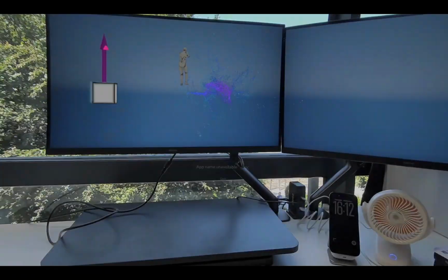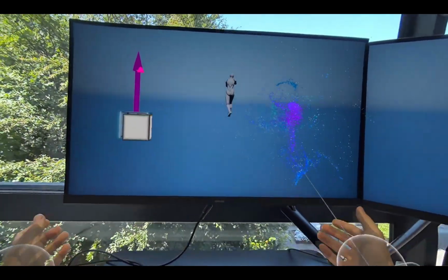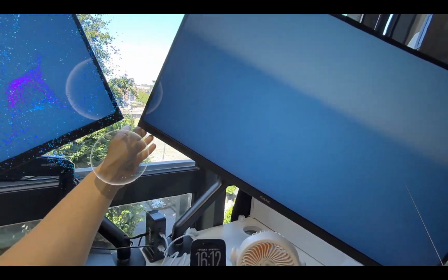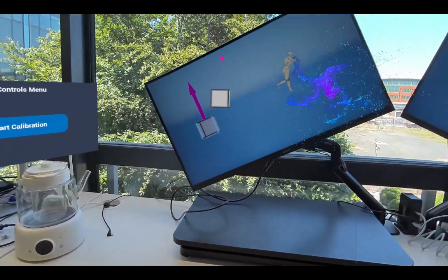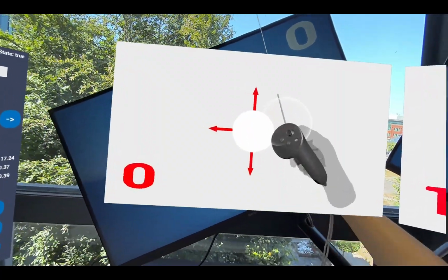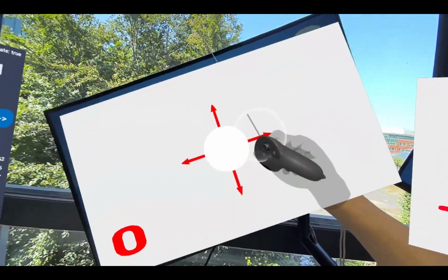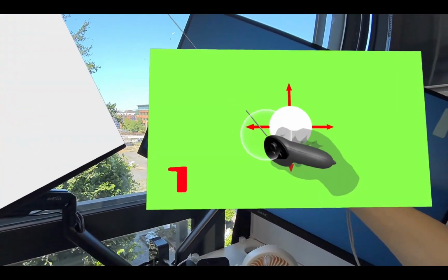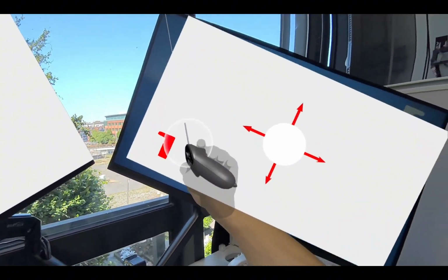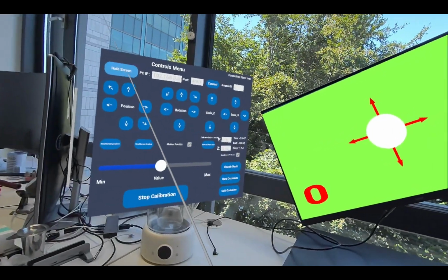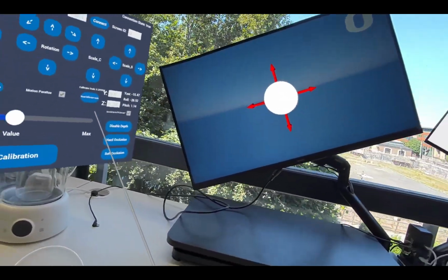In situations where the spatial relationships between screens are difficult to measure, such as this setup where the screens have been placed freely, we need to do more than align the primary screen calibrator. Enable Should Control PC Screen for each additional screen, and adjust each virtual screen so that its size, position, and rotation match the corresponding physical screen. The calibrated spatial relationships from the HMD will then be applied back to the screens in the PC nDisplay setup. This workflow allows screens of different sizes and arbitrary spatial arrangements to be calibrated.